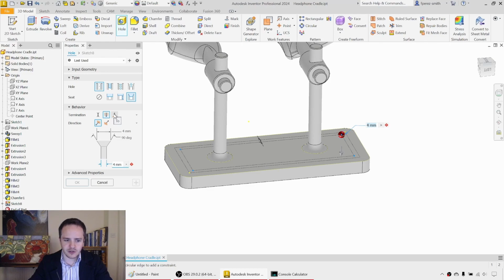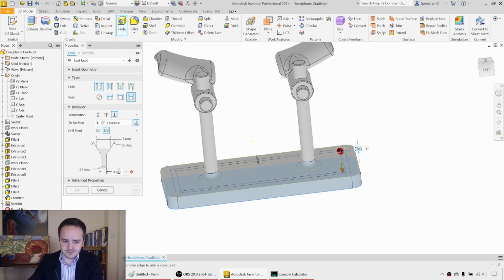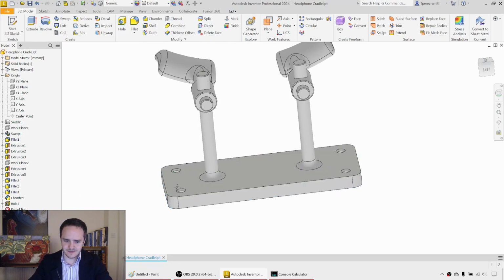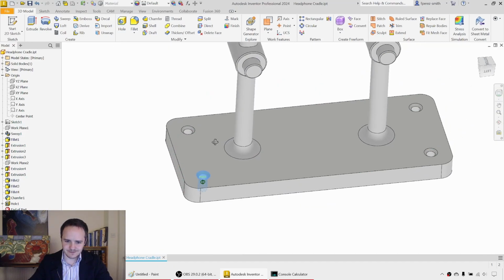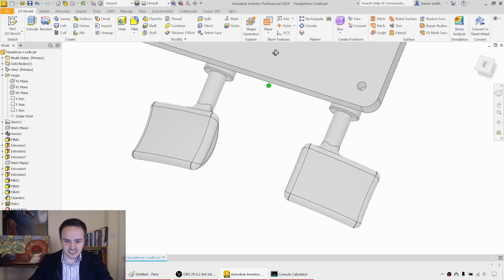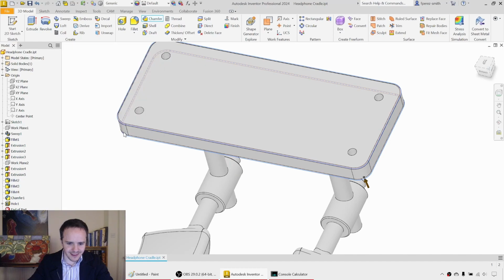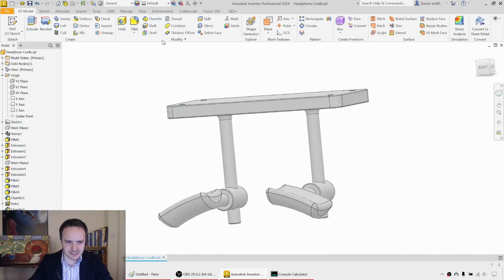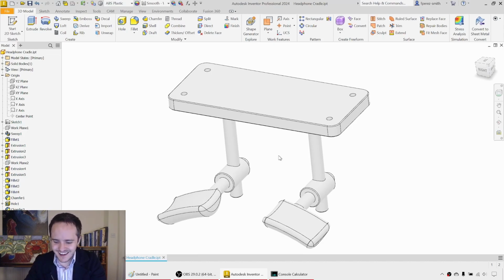It's doing fine. But if you wanted to, you could say 2 and go to that top surface there. For the diameter, make it the major diameter 4mm and for the countersink diameter 6mm. And click OK. And that should leave us with nice fastener holes. Good stuff. Okay. Last thing, we'll add chamfers top and bottom, 1, 2. And assign a material. So we'll change our material at the top here from generic to ABS plastic. Wonderful! Looks good! Yay, we're done!